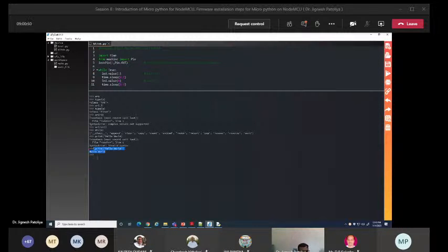So why is it interactive? Here we have the Python shell, and believe me, here we are running our code using the NodeMCU, the microcontroller. To get this shell, this binary file is there, and once we click on the download and run button, the binary file of this blink.py is deployed in this board, and we can see the LED going on and off. But if we want to store it permanently in this board, go to file, new file, similarly.